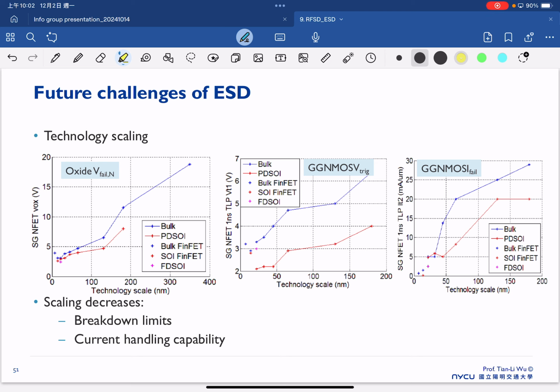And TDDB is also getting challenging as we move to the advanced node, because our dielectric is thinner, so we have very huge direct tunneling and our oxide is getting very weak, so we have to propose a high-K metal gate to make sure that our device has good TDDB. And if we talk about electromigration, in the advanced technology what we are trying to scale is not only the front-end channel length, channel region, front-end transistor or oxide thickness.